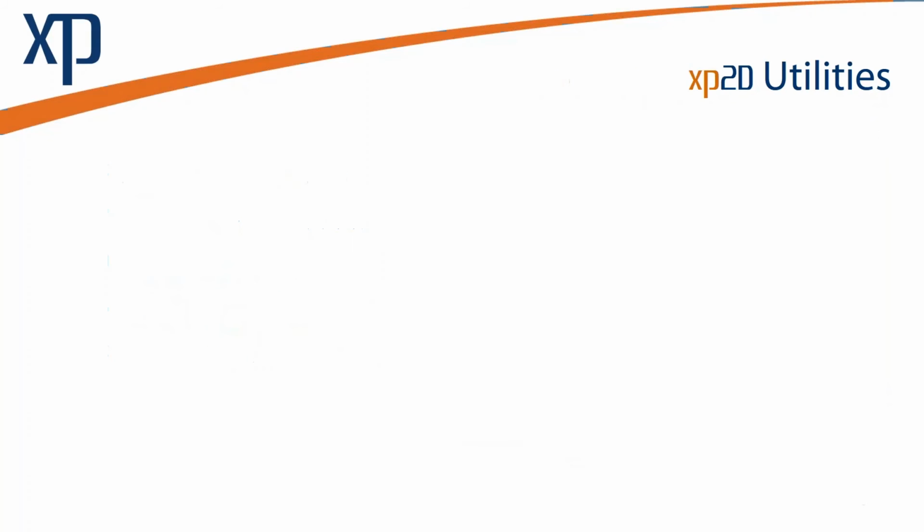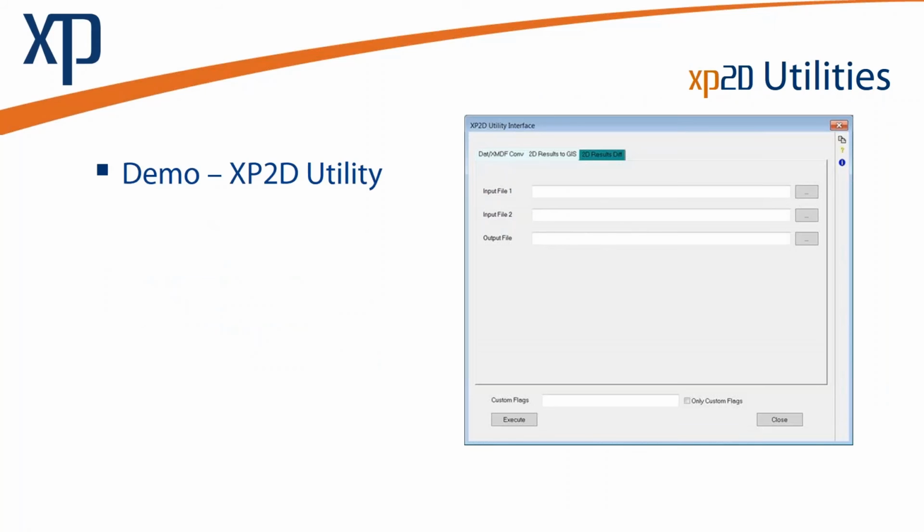Once we have that, we can use XP2D utilities to do a difference. We'll take the existing conditions and say our 5-foot diameter scenario and prepare a difference between those two elevation models. We can load that directly in xpstorm and add all those different results files on top of each other. It may get a little cluttered, but it gives you that ability to look at the results.